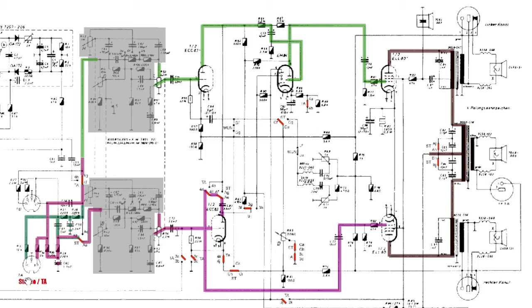When you don't activate stereo, this whole switching system here and here takes this triode out of the audio circuit and uses it as a driver for the Magic Eye tube itself, because it then gets a signal from this line at the bottom here rather than getting one of the channels. The audio is linked in one point only that goes through that tone shaping, through that triode.